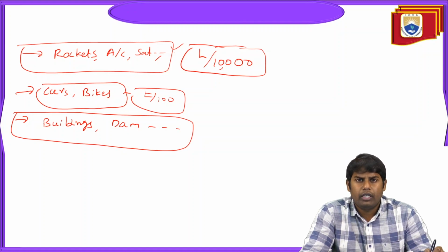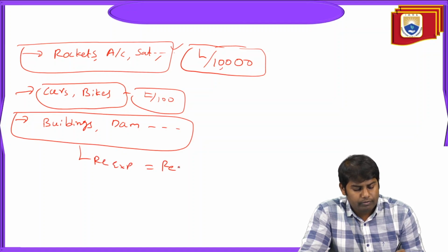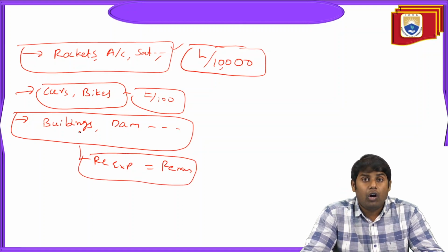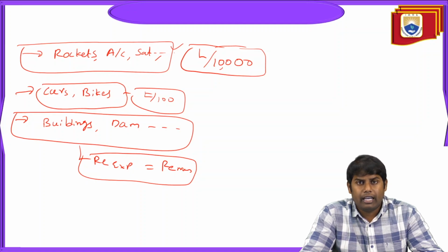They can keep those in the test section and perform the same experiment, keeping the Reynolds number Re of experiment equal to Re of numerical, so that they can compare the results. They will see how the ventilation system works, how the aerodynamic load acts over the building, and whether the flow is uniformly distributed or not. So these things can be answered.